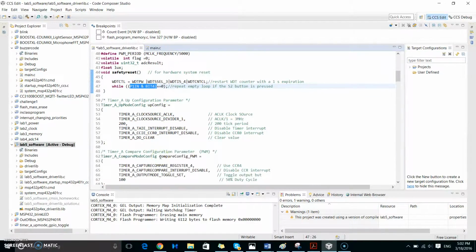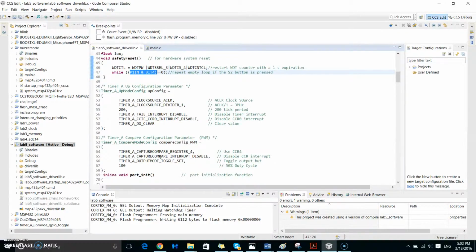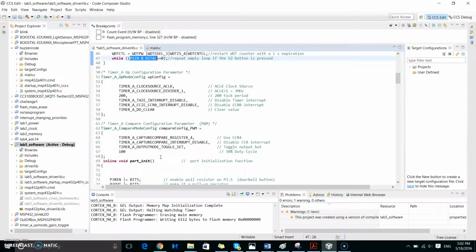As a next step, I have configured the Timer A module in up mode. This is to realize a pulse width modulation signal for the buzzer, and I've used this pulse width modulation with different duty cycles to emulate different sounds, for example, a real doorbell, a real burglar alarm, and a real fire alarm for different stimuli to my home monitoring system.